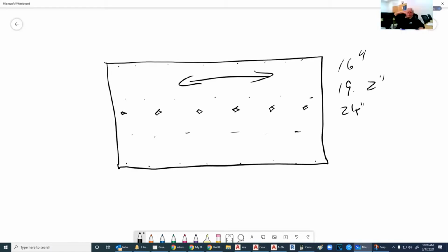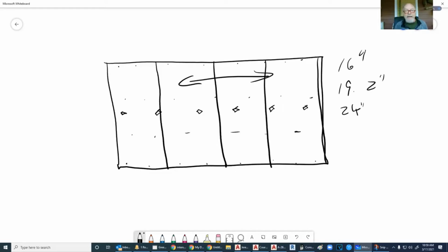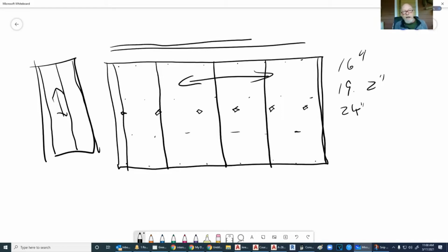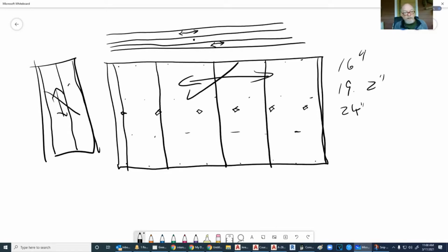When they talk about plywood, they will specifically say that plywood should be hung with the grain running between the supports, meaning like this. If we put it up this way, the grain is running parallel to the supports. Maybe it says perpendicular. I think it does. Perpendicular to the supports, because there is an odd number of plies, I'm just going to draw 3 here, it's going to be stronger in this direction than in this direction. Does that make sense?